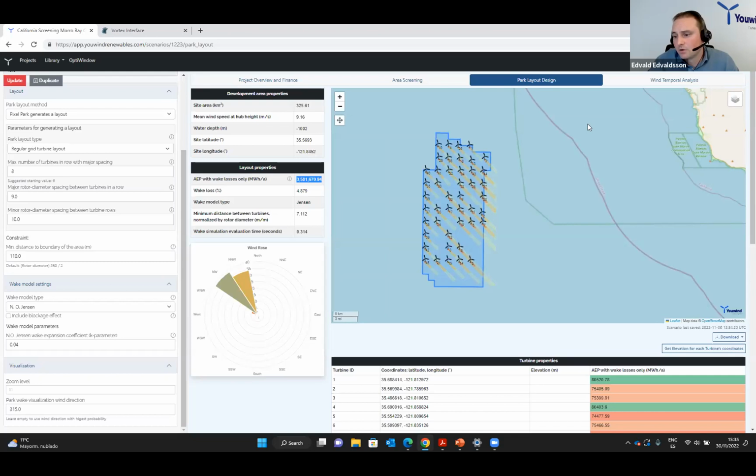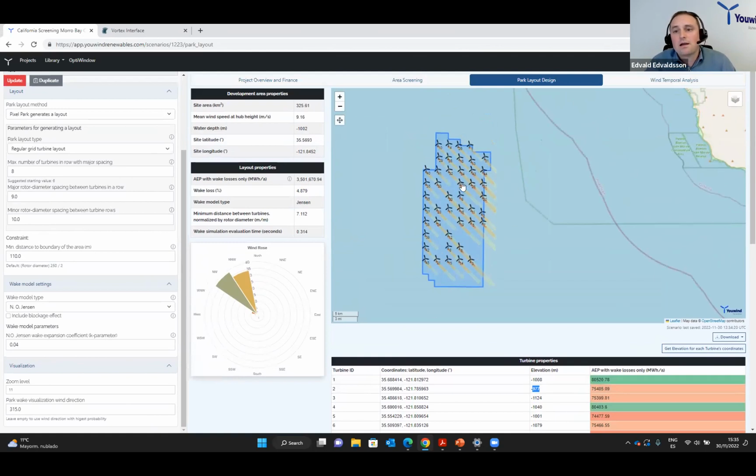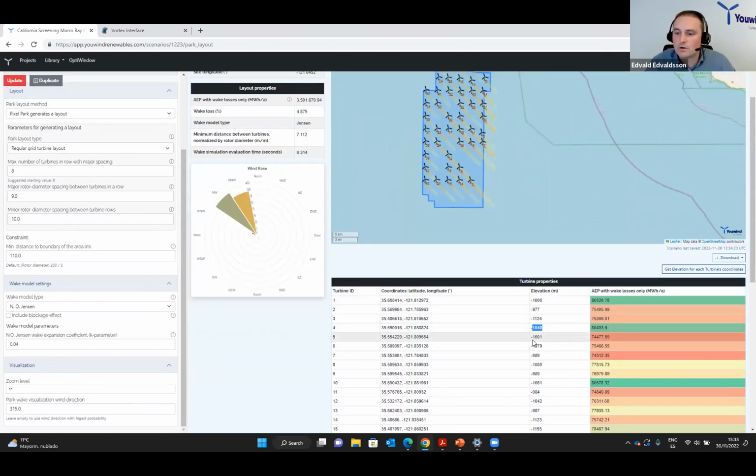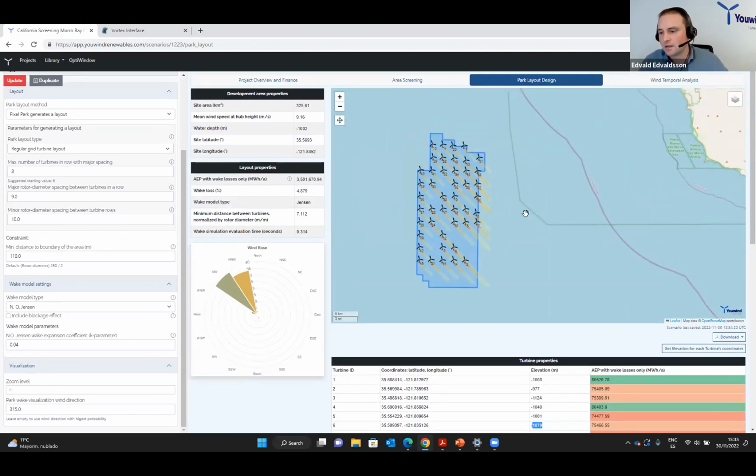Apart from that, you can also get the elevation or the bathymetry per position for the different turbines. If you click this button here, then with the API we have, for different positions you have a different cost function with it, as Peter was mentioning. And while combining all this, if we update the project, all the cost functions become part of each individual turbine, which means we are calculating the cost per turbine per position, which is very useful when evaluating the costs of the offshore wind farm.